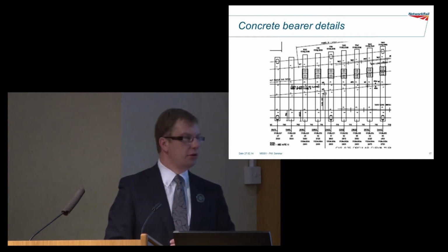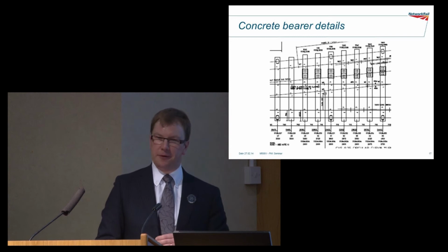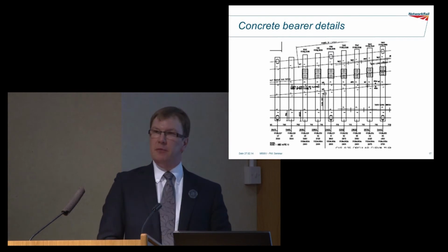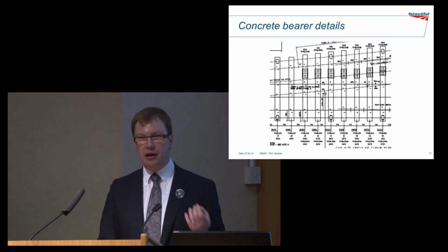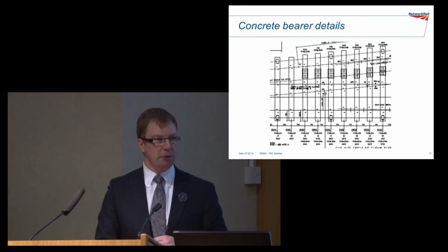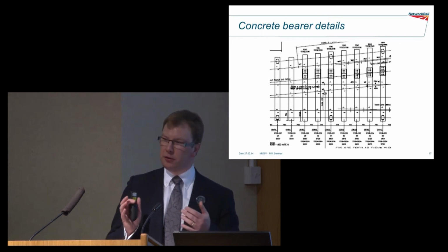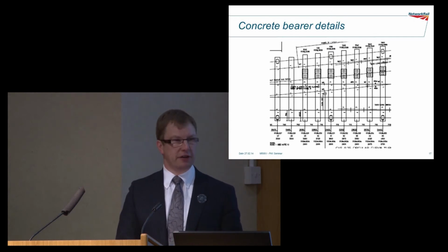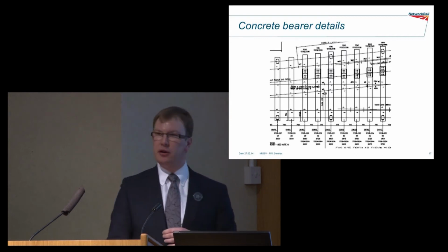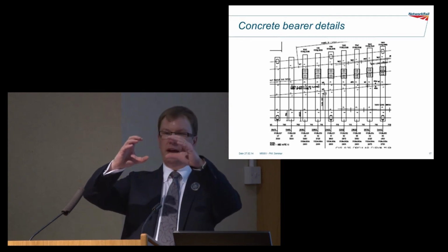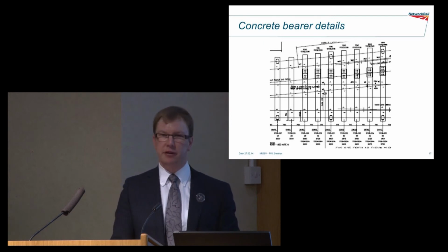We've actually changed the rules around the way the housings sit, because it was really a change in moving to a higher toe load clip and a more resilient pad. So we're moving more to a pad and clip arrangement used on plain line sleepers. But there was quite a big assumption, because traditionally on bearers for S&C, the housings were always a set distance from the centre line of the bearer. But what we're doing here is actually, as we rotate around, we're rotating the rail seat. So the whole thing, the pads, the housings, the whole thing's rotating round.